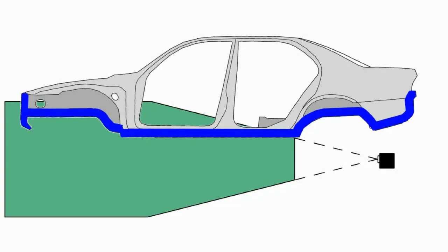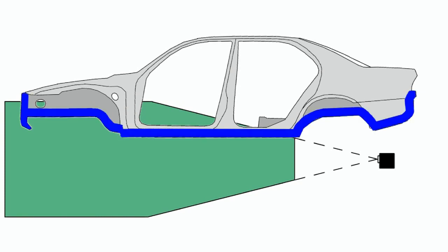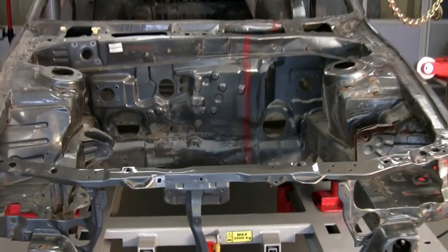As soon as the system combines the results of the two series of measurements, the monitor displays the plane of the whole vehicle's lower section. Now we have to add to the plane the coordinates of the reference points in the engine section, the attachment points of dampers.